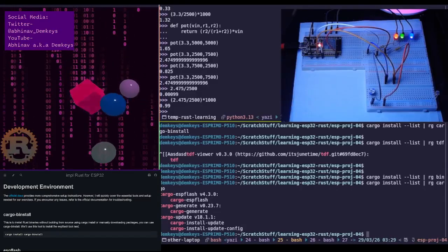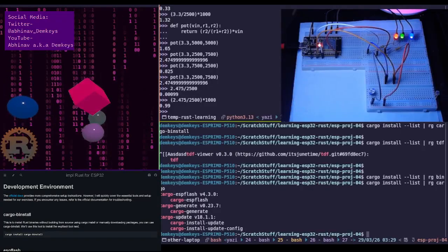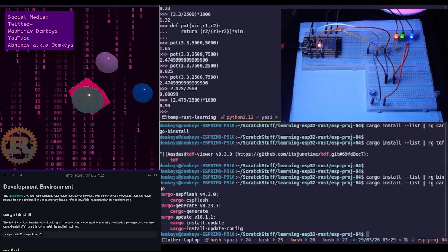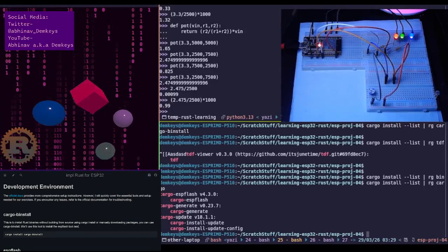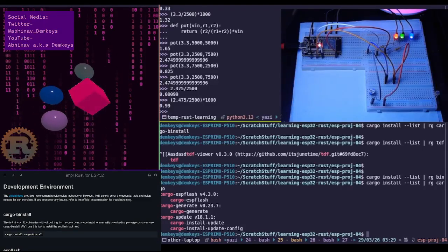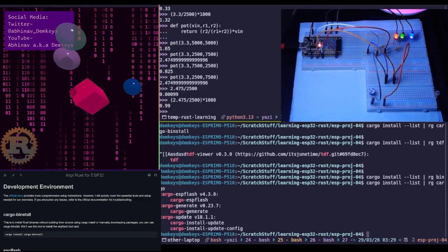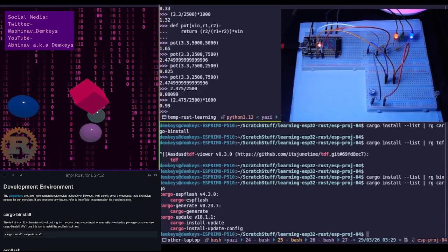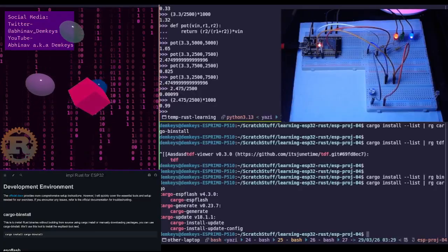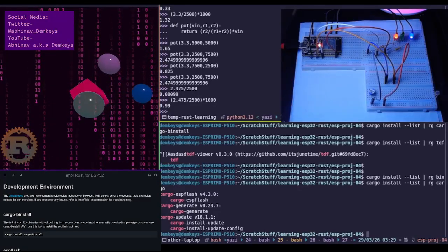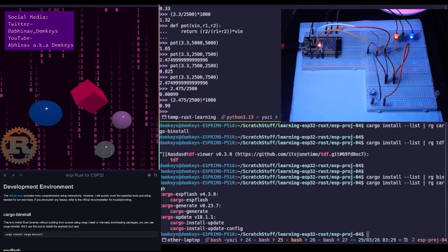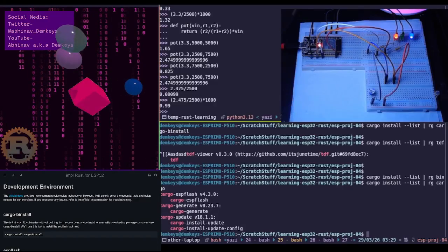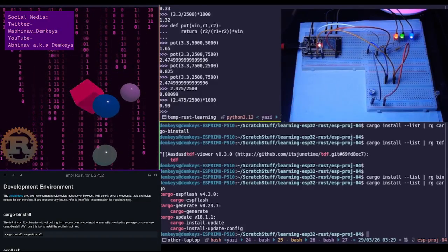To flash the binary, you need something called the WCH link E. This is a cheap hardware programmer slash debugger, or flasher slash debugger, that you can get. It's a proprietary device by WCH, which supports the protocol required for flashing a binary onto the CH32V003. And it turns out the E part is also necessary.